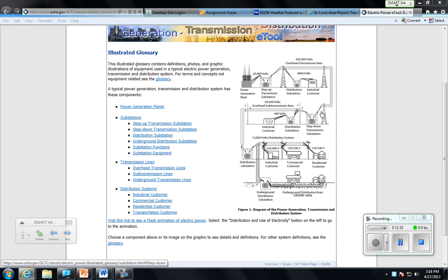And then you're going to send it on. You're going to start stepping it down as you get near a city so you don't have such high voltage running through the power lines in the city. Maybe to an industrial customer that uses 440 volts, or you send it overhead to another distributor substation. So here is maybe a retail business that needs 220 or 440 volts. Here's somebody who runs on regular standard household current, or here's an actual house. And so into these things are sent 120 or 240 volts using transformers on the poles.